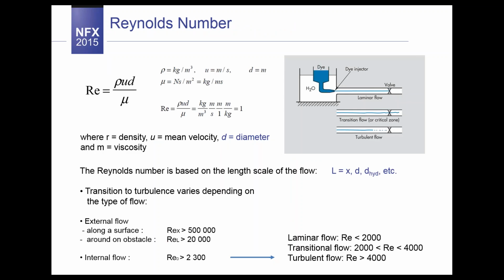The next slide refers to the Reynolds number. That's basically the dimensionless parameter which characterizes this type of flow. If you take a look at this parameter, at the top of this equation there are several data like density, diameter of the pipe, or, let's say, characteristic dimension. And at the bottom we are observing the viscosity. If you take a look at this calculation, of course it's easy to prove that this parameter is dimensionless.